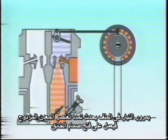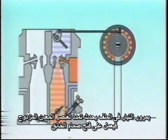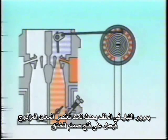After the engine is started, current will flow through the electronic coil. This will generate heat, which will cause the bimetal element to expand and open the choke either slightly or all the way.